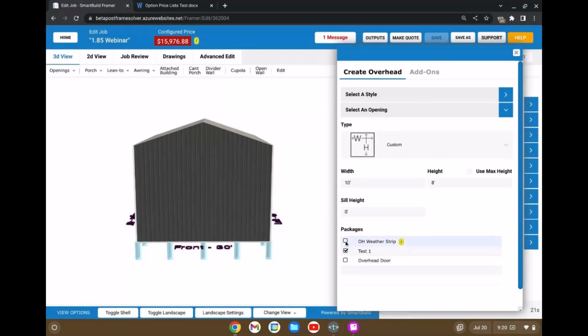And so one new feature here is we have the sill height for the openings now. The way that we've set this up is that for the openings, you can put in a sill height, and it's going to put the bottom of the opening at that sill height, as opposed to the header height for the windows. We're doing a sill height. It'll just give you the bottom of this opening. We can do some changes to that. If that doesn't really make sense to you, or if you want to see something else, let us know. But that's how we have this set up right now.